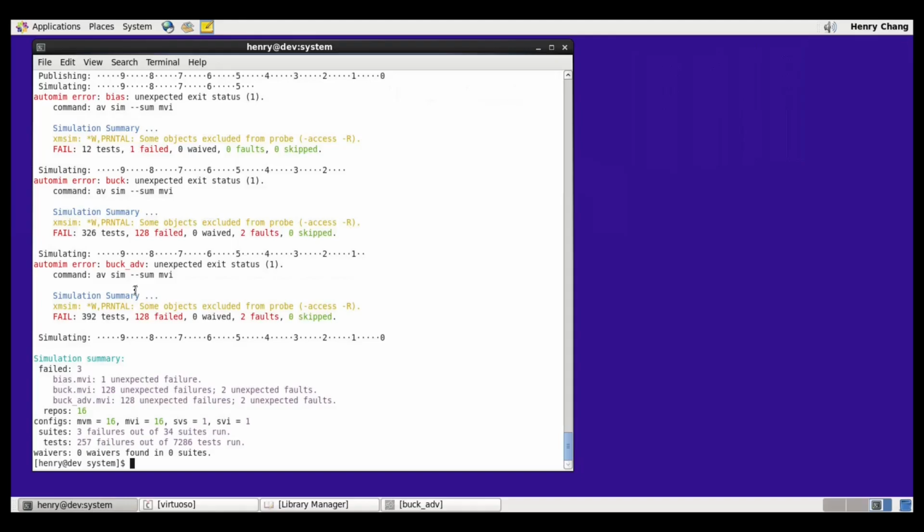In the buck and the advanced buck, the current source from the bias of the ramp generator received the wrong current and issued a fault as a result. So while we can't know exactly how many times the fault would be triggered, we do see that there are faults in the buck and the advanced buck simulations. We'll be looking at the text output and the waveforms to examine these faults in detail.